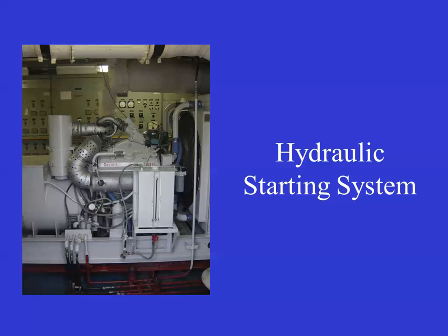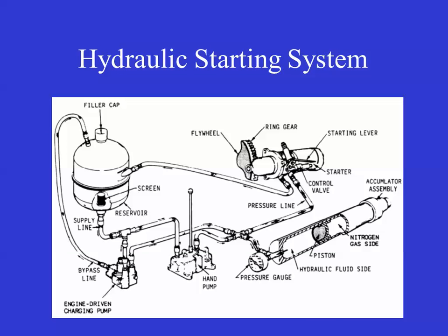A much better system, I think, is the hydraulic. Hydraulic is very, very good because it gives you a high amount of torque and a high starting speed. They're expensive, but for a small diesel, it's a very, very good system. Now, to store the hydraulic fluid, you have an accumulator. Be very, very respectful of a fully charged accumulator. They're typically 2,000 to, I've seen up to 4,000 pounds. When you get into high pressures like that, you better respect the amount of energy that is being stored.